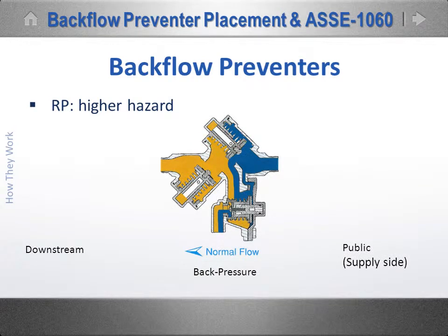Finally, consider a failure of both check valves. As long as there is no back pressure or back siphon occurring, water will be delivered normally. But any back pressure event will flow the delivered water to the relief valve at head pressure again and again. No water will escape back to the street because of the placement of the relief valve.